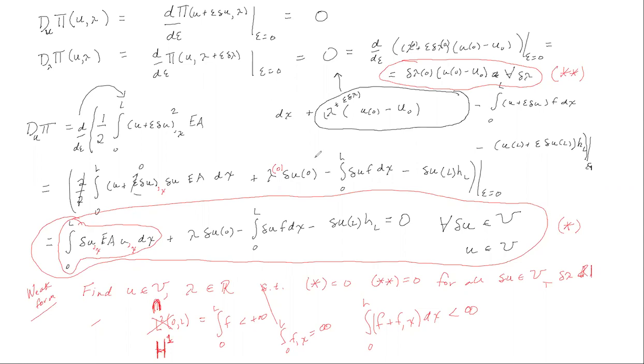And that's extremely important. Well, you're solving for the strain at every point in that structure. Is that what you're getting at? Well, it's hard to tell. I can't tell by looking. What I'm saying is, you can never take a weak form without solving for the strong form. I would always solve for the strong form corresponding to your weak form, because that will tell you the equations that you're solving for. And we're going to do that next. What you'll see is they're called the Euler-Lagrange equations, but it's also called the strong form.